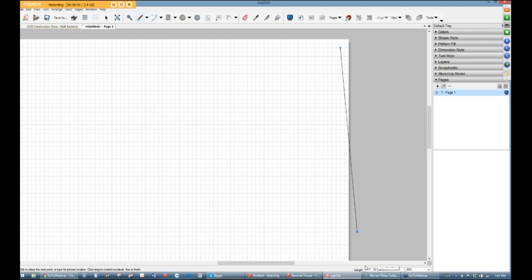Down here in the bottom part of this screen, it says length. And you can see it dynamically changes as I move. And with the grid on there, it's pretty clean. It says right now 1.5 inches. So you can look at it and take it out where you'd like. Let's make it 2 inches. I'm just going to make a block for a title.